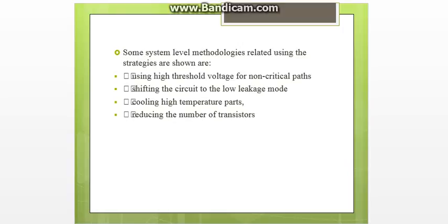Some system level methodologies related to using these strategies are shown: using high threshold voltage for non-critical paths, shifting the circuit to the low level mode, cooling high temperature parts, reducing the number of transistors.